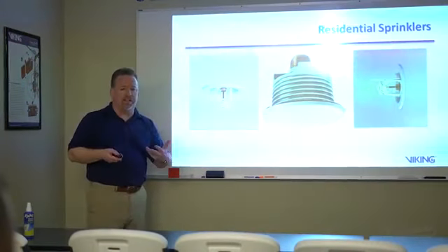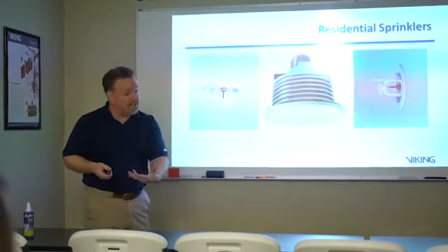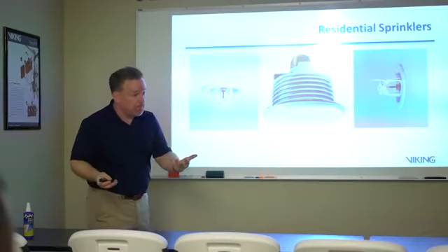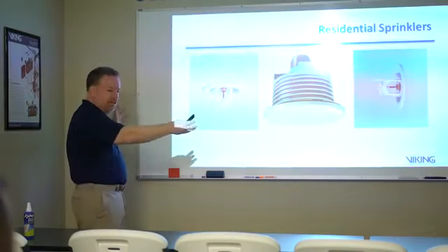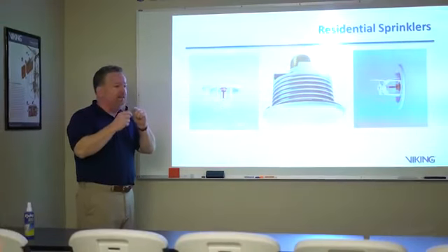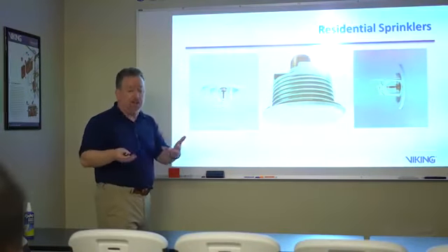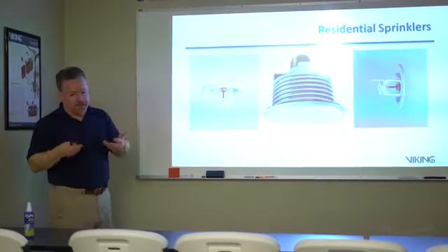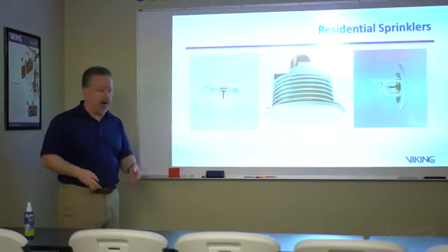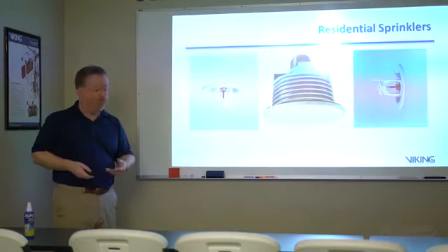And again, with residential, in order to cover these areas, you had to provide life safety, whereas other sprinkler systems were basically designed for property protection, everything else we've been talking about up until this point. This particular sprinkler, and the whole system, was designed to provide enough water so that people could get out of the building and survive. If the system ran out of water at that point in time, that was fine. It was more of a life safety system: get the people out.